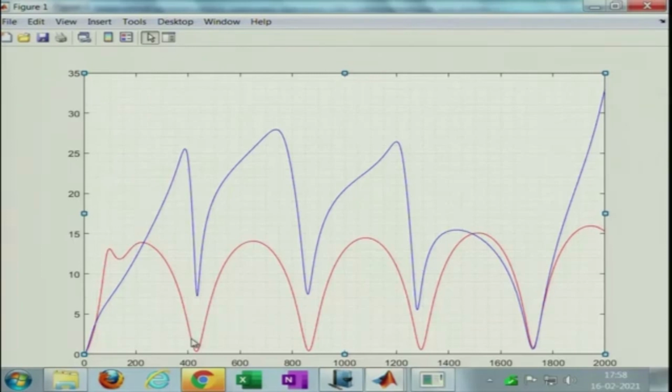And another thing that we must note is that perforated impedance is a function of many variables, which include hole diameter, thickness, and your mean flow, of course, and porosity, of course. So they also have to be investigated. If we were to do it systematically, we can find a generalized curve fit based on expressions for end corrections as a function of all these parameters. That will require a lot of trial and error to find out.